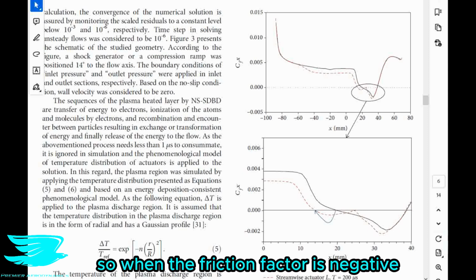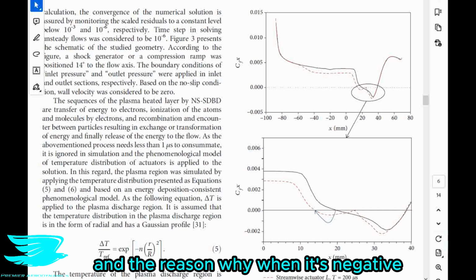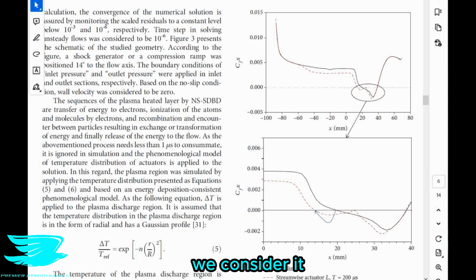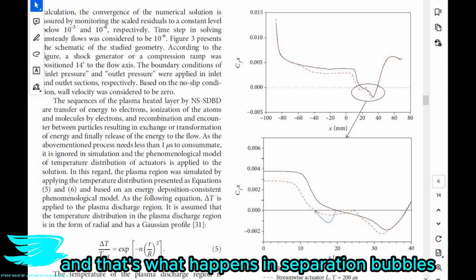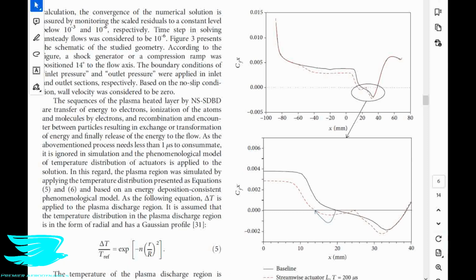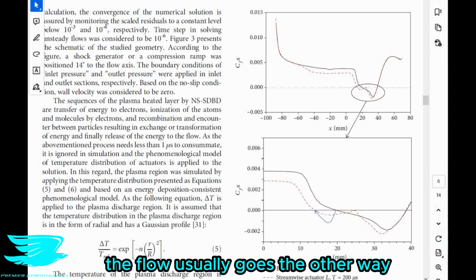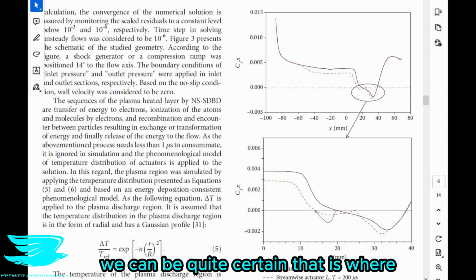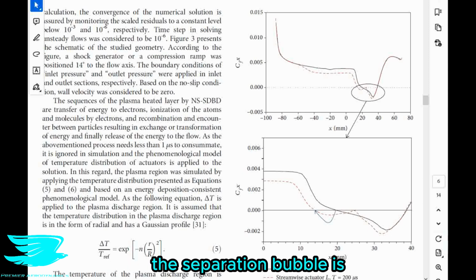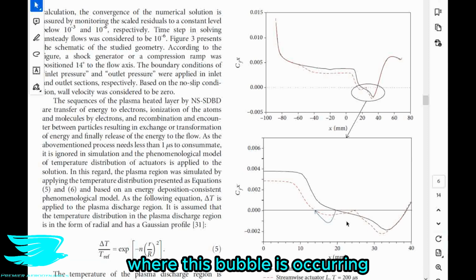When the friction factor is negative, the flow is deemed separated, and as such, we can see the exact effects the plasma generator has on the flow. The reason we consider it separated when it's negative is because that means the flow is now moving in the opposite direction. And that's what happens in separation bubbles. When you have the flow detaching and then reattaching in that separation region, the flow usually goes the other way. So when we have a negative friction factor here, we can be quite certain that is where the separation bubble is. So that gives us a very quantitative way of telling where this bubble is occurring.